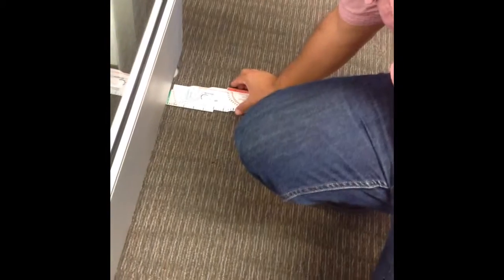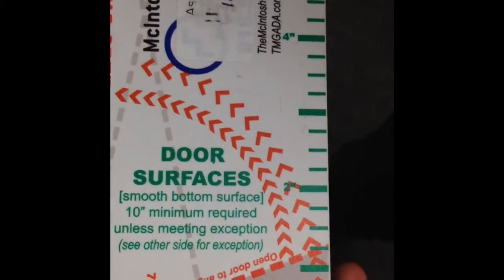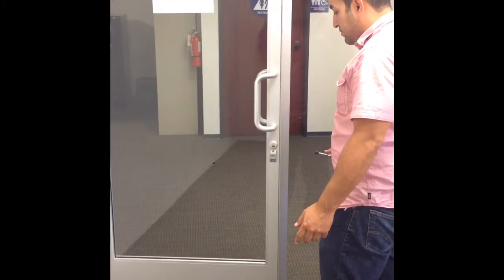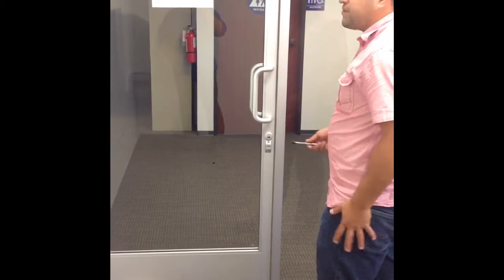You will position the door so it says 90 degrees. If you want to know what I'm looking at, it says right here, place edge along floor. This is the 90-degree mark. You put that edge right on there, then close the door and count. Use your phone to time it if you want to be more accurate. 1001, 1002, 1003, 1004, 1005. About 5 seconds to close the door.